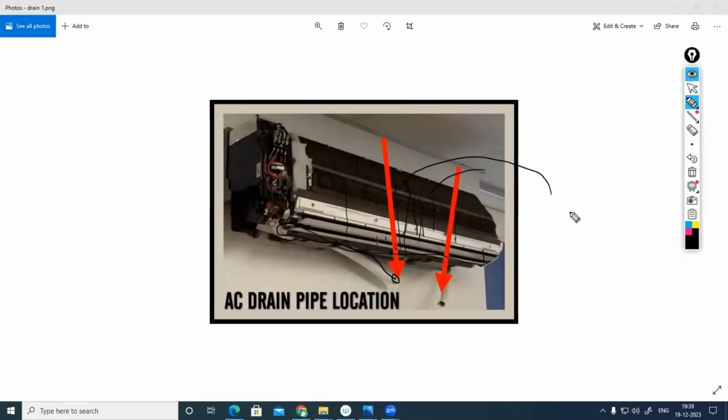Okay, anyhow, that's another story. Normally in residential homes, what we do is free discharging. We take this pipe outside, then we free discharge to the atmosphere. Okay, that's the fourth option. So when we are installing your AC machine, we make a hole. Through that hole only, we take the pipe connections outside. Sometimes when the service technicians are making the hole, they might make it straight.